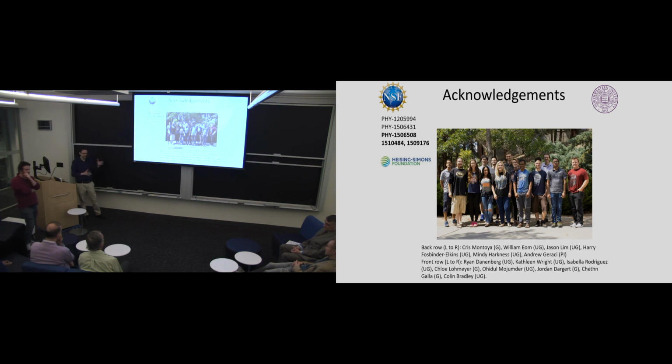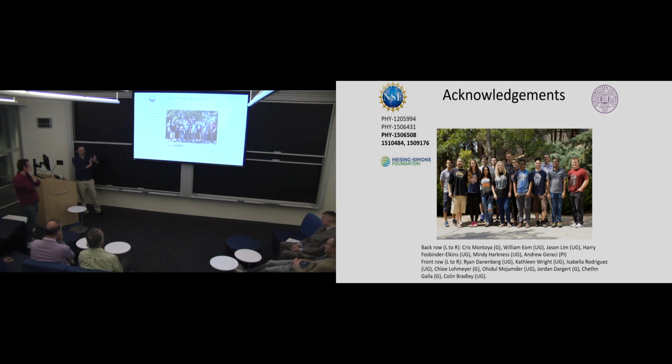The drive mass device itself, as I mentioned, we had that elaborate polishing process where we had to turn it upside down and get rid of the silicon. So there we are worried about any corrugations in the electromagnetic signals that would occur at the period of interest, but we can get the material flat enough with a uniform enough film that we don't see any evidence of electromagnetic effects. We had a similar technique in the Stanford experiment with cantilevers, and it was sufficient for that, so we expect it to be good enough for this too.